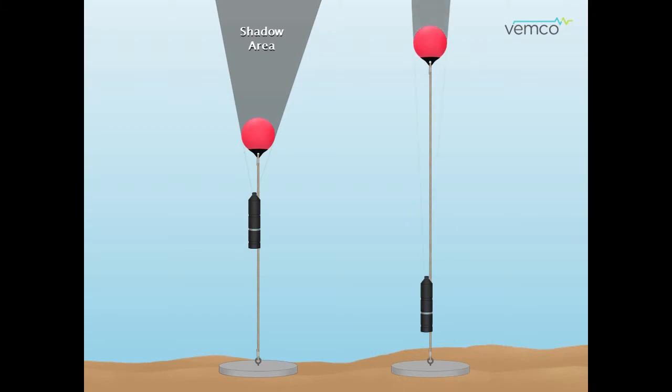Other mooring considerations to keep in mind are not to have any hanging or loose material near the receiver that could bang against the receiver or something in the area and therefore increase the noise level. And be sure that there are no mechanical coverings around the head of the receiver, like neoprene, that could impede the acoustic signals.